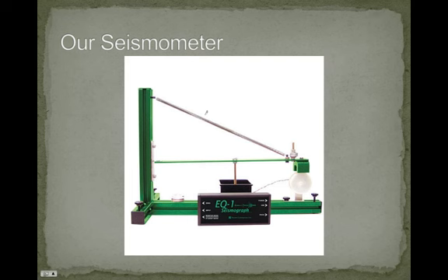Now, this is our seismometer, which is the EQ1 seismograph. It is down in the first floor in the side room. And the way this works is pretty simple. In here is the coil of wires. And this is a magnet. And as the vibrations come through, the magnet will move up and down, which causes a change in current, a change in charge of electrons. And they flow through to this little device which connects to a computer, and that reads it. Inside of this pan is some oil that keeps it from moving too much. It slows down its motion.